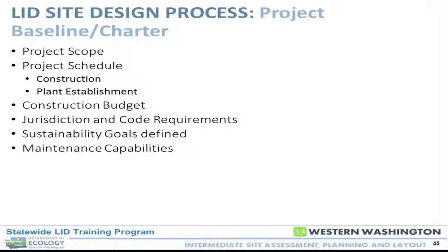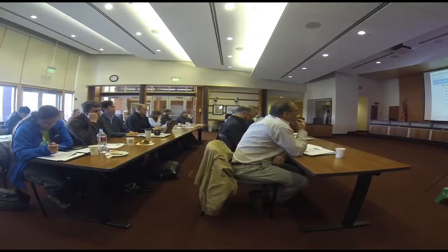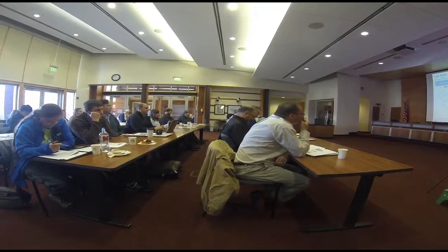Also, another key aspect is understanding when you're going to establish the plants. If you're not going to try to develop an irrigation system, you need to plant those plants during the wetter seasons. That way they don't dry out and die. Understand your construction budget. We all want to do a great design, but understand what the limitations of those budgets are and how you can use LID to actually make that construction budget fit within there. If design is done correctly, it can be competitive with a conventional design.